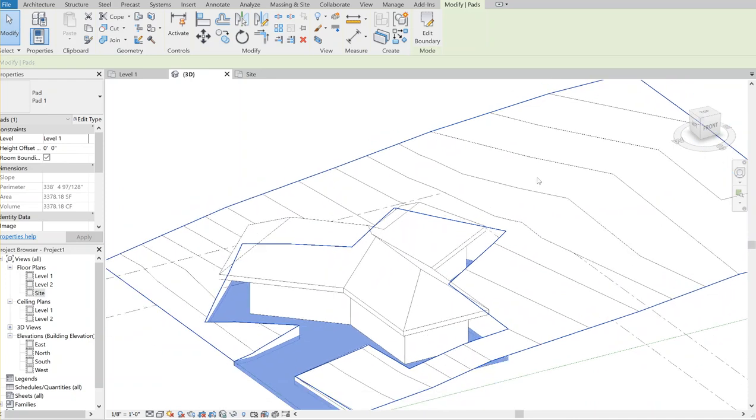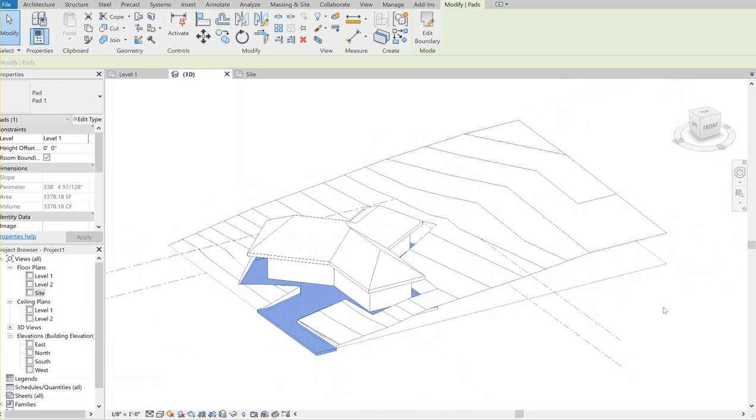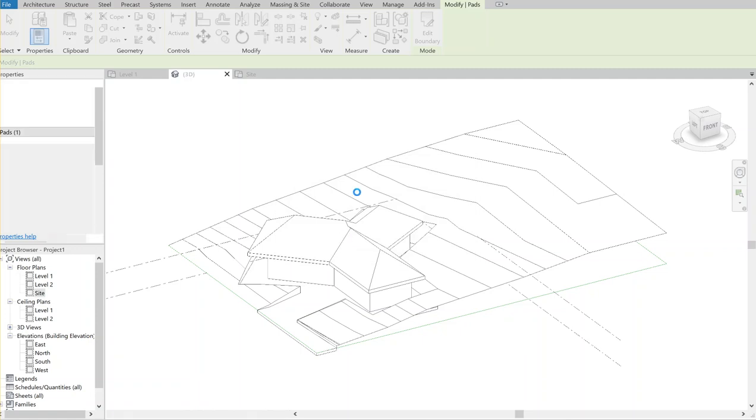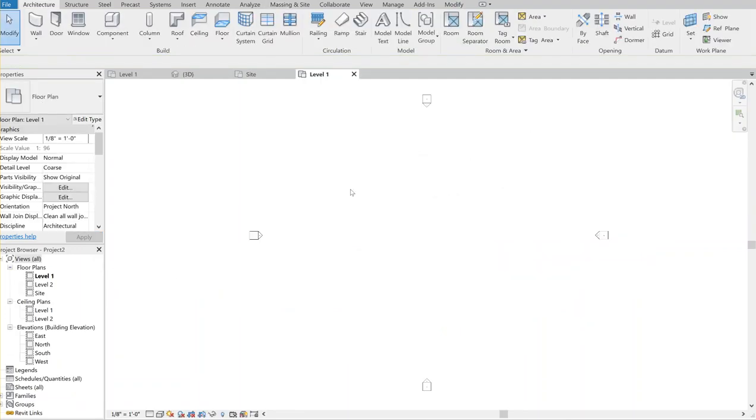I'm going to erase or start a brand new drawing, and I'm going to simply go to File and Create New. When you're creating a new one, select the architectural template. Please do that because commands are not available in the other templates. The architectural template enables you to give the multiple commands that are going to be necessary. Okay, this is your screen.